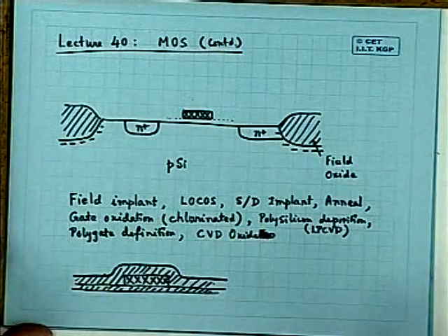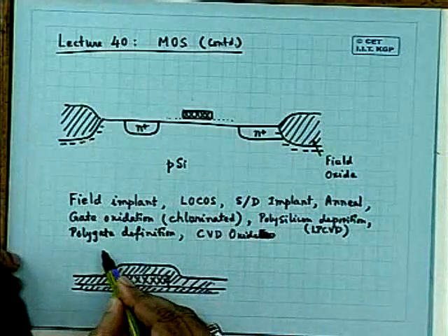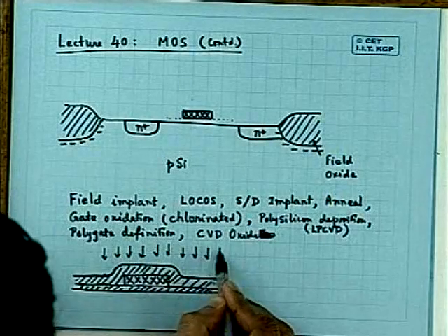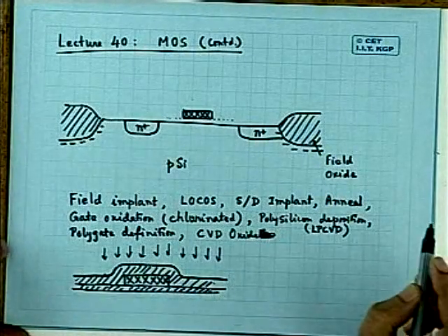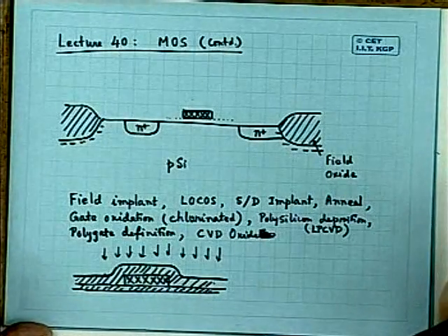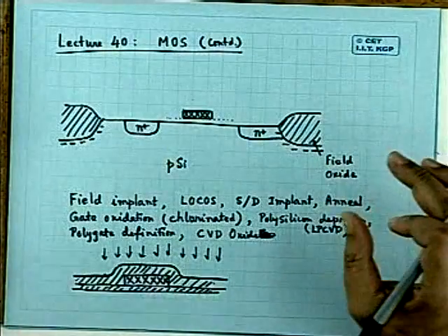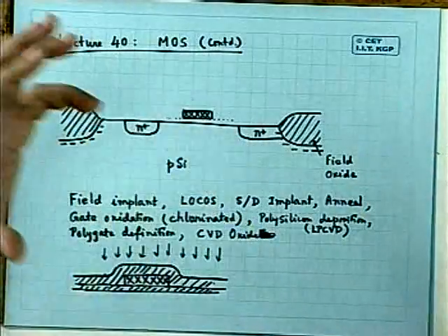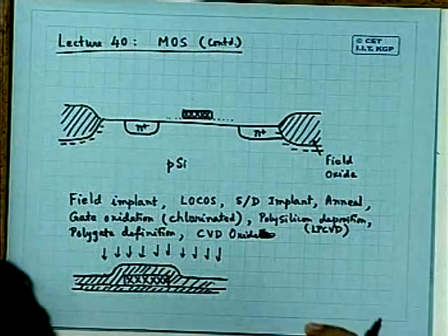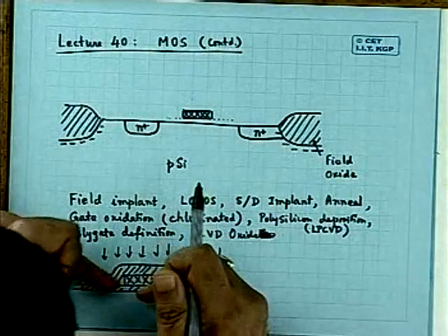So CVD oxide, then do some reactive ion etching. That means you bombard it with some reactive ions, like fluorine ions, usually fluorine ions or fluoride, that's SF6, either using CF4 plasma, C2F6 plasma, SF6 plasma, sometimes a mixture of fluorine and chlorine. There are various techniques. You do some ion etching. So ion etching, what will happen as a result? Gradually, ion etching removes molecules from the surface.